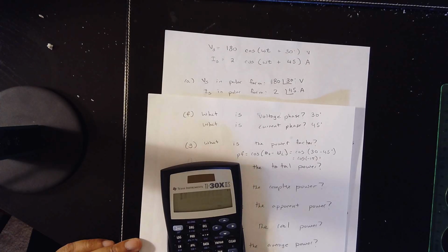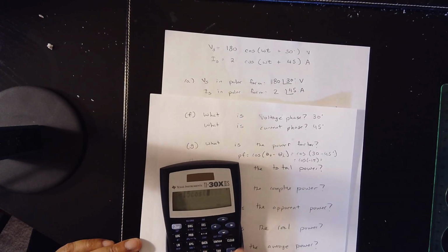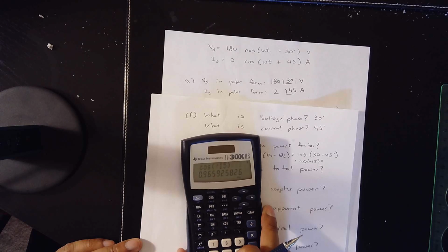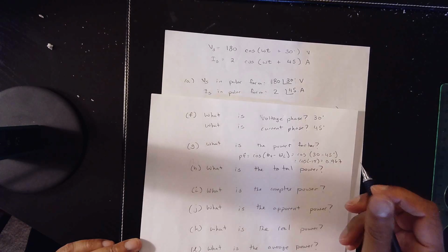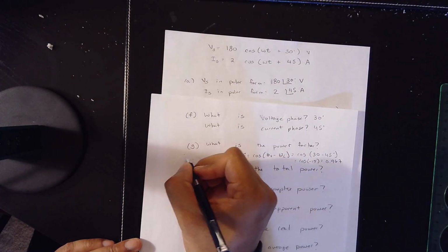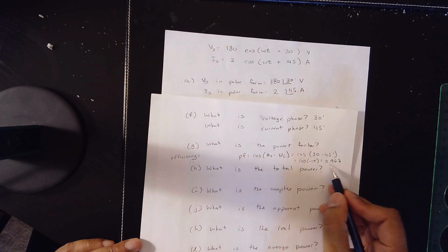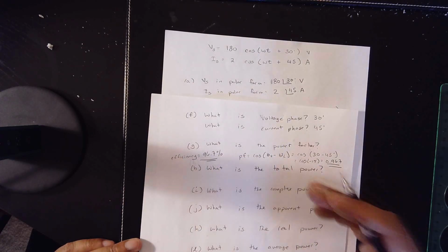You take 15. Really it is going to be a positive number, but you could take 15 minus, and take the cosine, cosine of 15, equals 0.965, or 0.967, right? So 0.967. So what is the efficiency? If I ask you the efficiency, I didn't ask you earlier, but what is the efficiency? Efficiency is basically 0.967 or 96.7%. That's where you get the efficiency of your electricity.